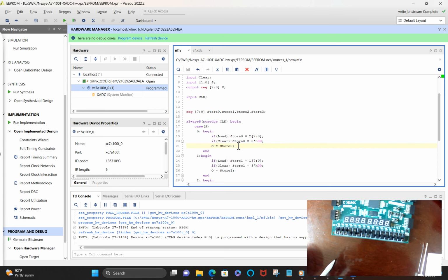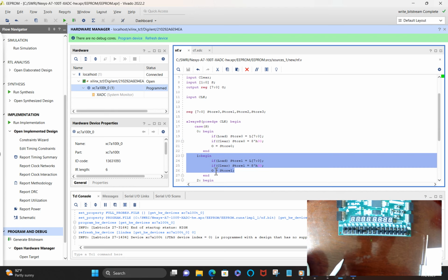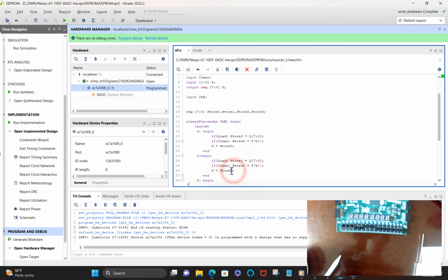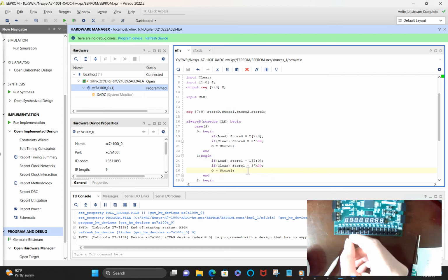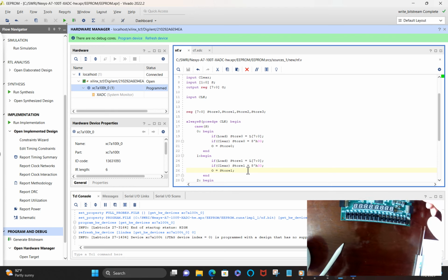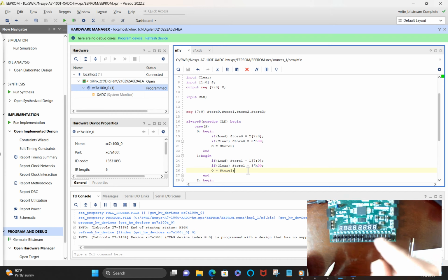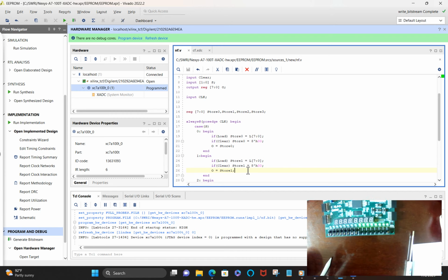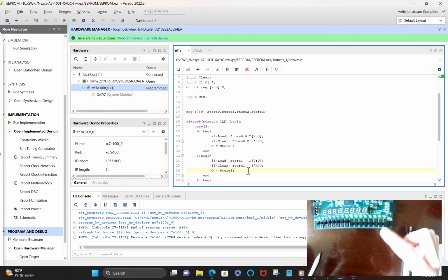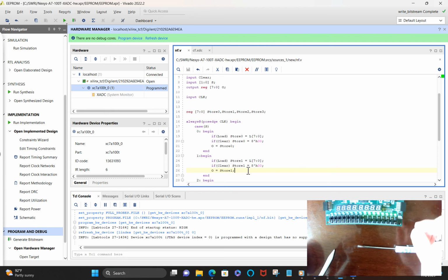If we switch to state 1, it goes away because we're no longer in here. Now output O is showing the value that's in register store 1, which has not been initialized yet. So let's make this one be all ones. And it keeps that. If we go back to state 0 or address 0, it retained the value we last put in. If we go to 1, it has that.